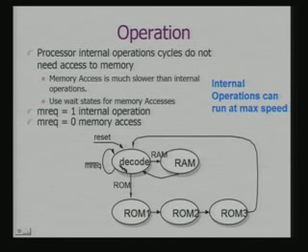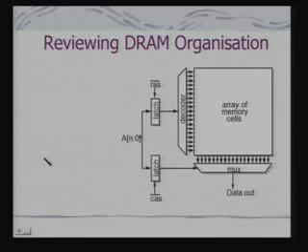So, when it is MREQ 0, effectively I go to the RAM, decode, and come back, and when I am doing the access here, it is a ROM access, and corresponding to that there will be the wait state which would be generated. So, actually this MREQ signal indicates at what point the wait should really be made active, when we are doing a ROM access.